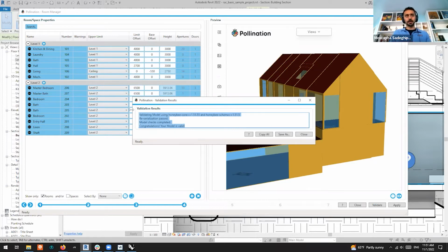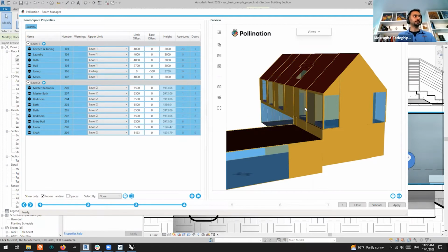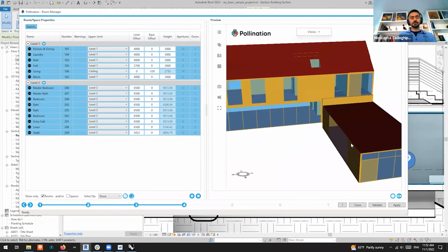We don't have the knowledge to know that. But we know to check that all the apertures are inside the parent face, that there are not two apertures on top of each other, and that the area of the apertures in a face is not more than the total parent wall. You think those things are not going to happen to you. They will happen to you. With Revit models, there are so many things that can go wrong. This is a good thing to check all the time to make sure you have the minimum correct things happening, at least in your geometry. Any questions?